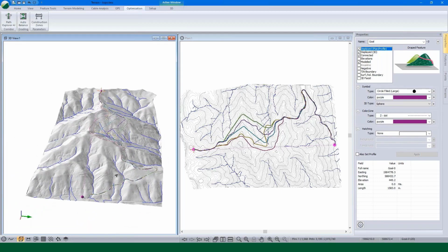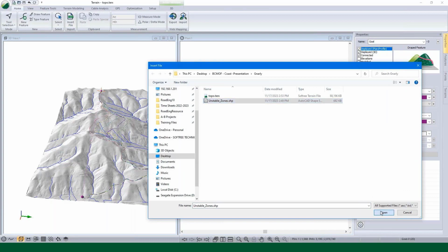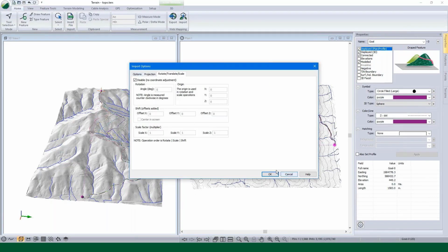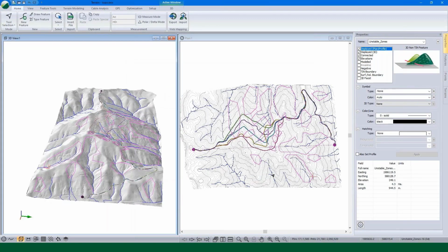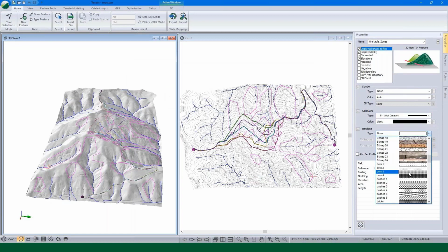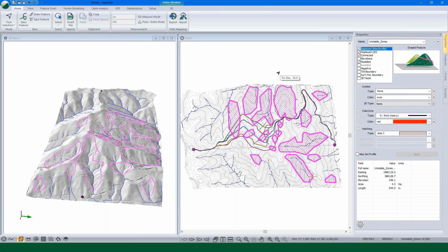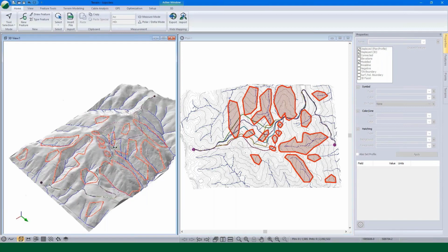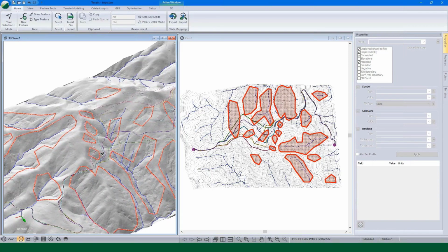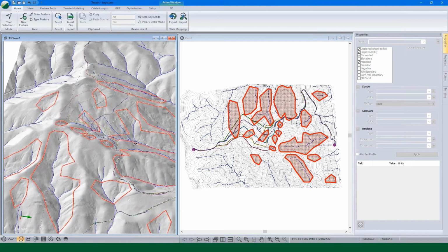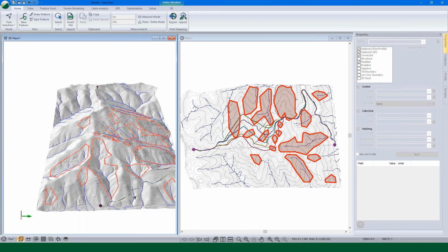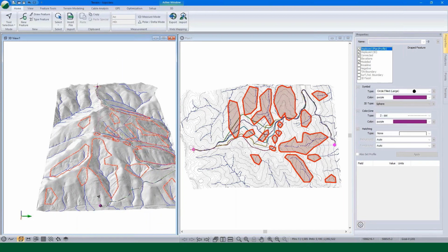So where it's initially suggested is not really an option. So we're going to add in some polygons, and we're going to use those polygons to act as a deterrent. If we delineate all of the areas we don't want to be, something that when I ran this, I wasn't sure if there was actually a feasible solution to avoid all of them. So we could have used those as no-go areas where it would have been a firm rule, the alignment's not allowed to go within those polygons.